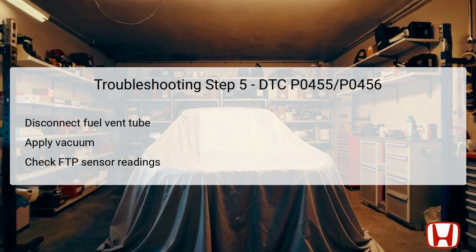After applying vacuum, if the sensor voltage increases more than 0.2 volts, the system is functioning as designed, and you can proceed to the next step. However, if the increase is less than 0.2 volts, further troubleshooting is warranted.